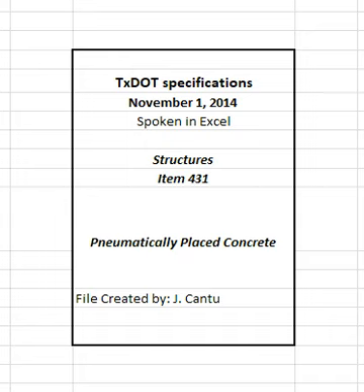Clean mixing and placing equipment at regular intervals. Inspect the nozzle liner and water and air injection system daily, replace worn parts as necessary. Do not reuse rebound or overspray concrete. 3.4.2 Dry mix process. Use a compressor or blower capable of delivering a sufficient volume of oil-free air at the pressure shown in Table 2.